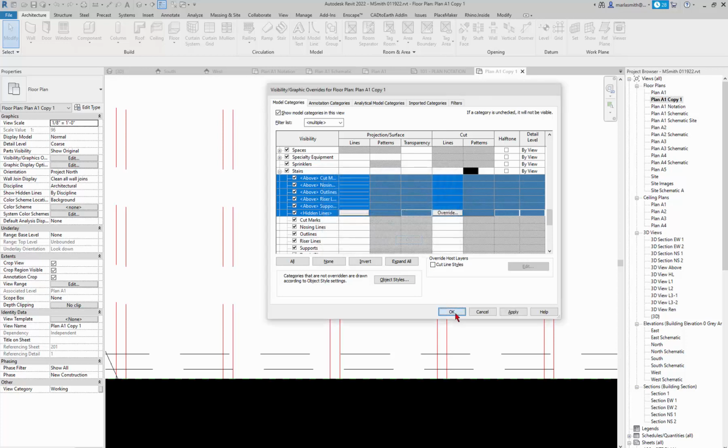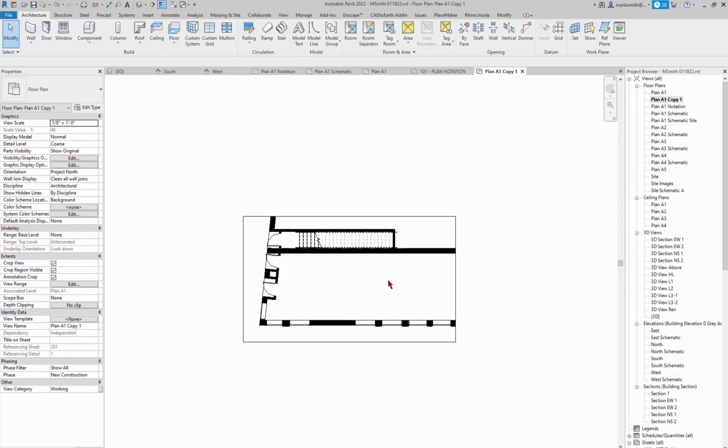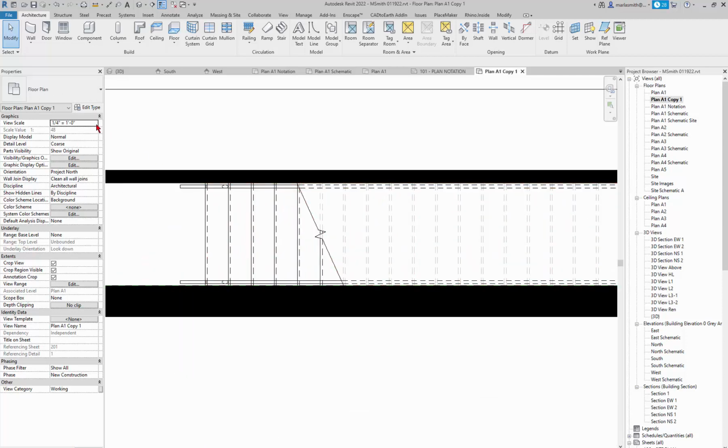Okay. So you can go in and set any of the new floor plans. I can also come in here and change it to 1/4 of an inch. So if I go in and update this guy, now it's 1/4 of an inch. You can see it actually changing the dashed lines, right? Because, right, if I change it to 1/2 an inch, it will actually update those. Everything in Revit is annotative, so it will update based on the scale of the drawing.